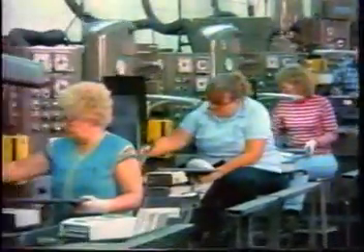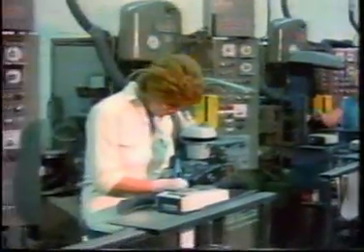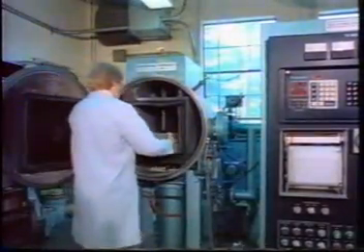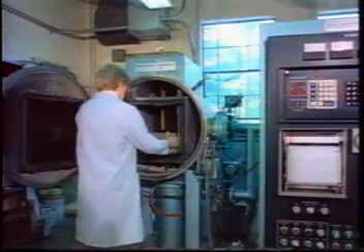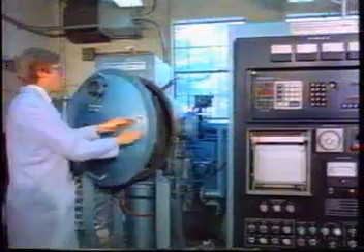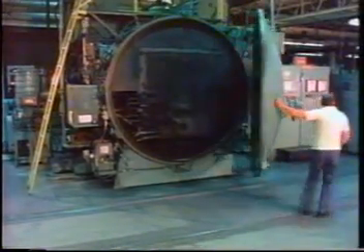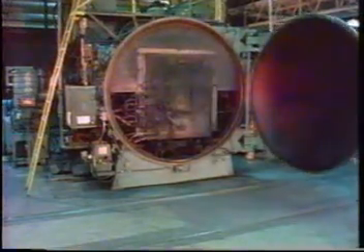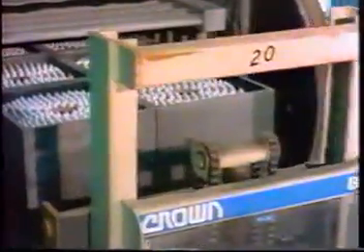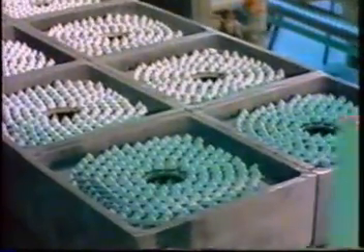The forming is usually done in mechanical presses, where the powder is pressed into shapes approaching that of the end product. At this point, the product is referred to as being in its green state, meaning it has not yet been consolidated by heat, or as we call it, sintered. In some instances, the product is pre-sintered at temperatures up to 1200 degrees Fahrenheit. This process hardens it to the consistency of chalk. In this state, it can be machined before final sintering.